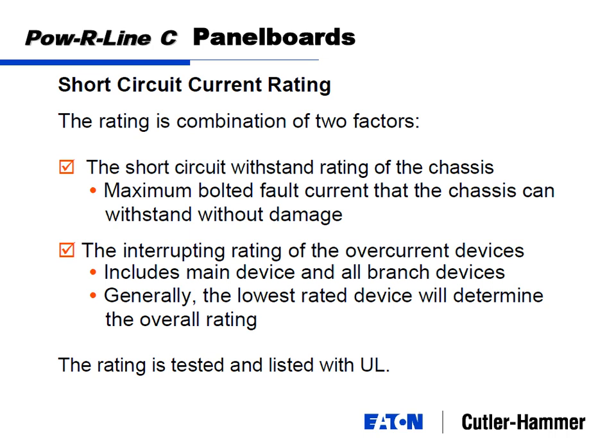that's the maximum fault current that the chassis can withstand without damage. And that's classified as withstand. When you hear the word withstand, it pretty much means what it sounds like. It's the ability to sit there and withstand that much current without damage.